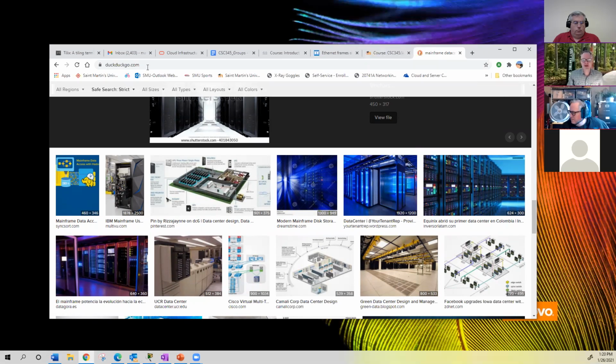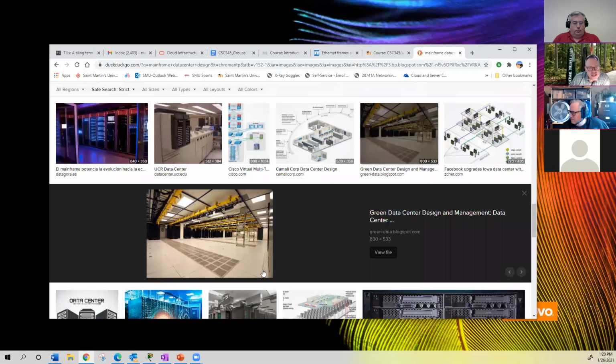So here's one, before they've put the racks in. And you see that all these perforated tiles here are in the cold aisle. And then the fronts of these cabinets will be put in right here next to the perforated tiles. The airflow will come up through there and get pulled into the front of all the servers in those racks, and then exhausted out the hot aisle, which is on the back. Really, two cabinets together in the middle there, the two exhaust sides will face each other so that heat just goes into a hot aisle and then escapes up above. All right.